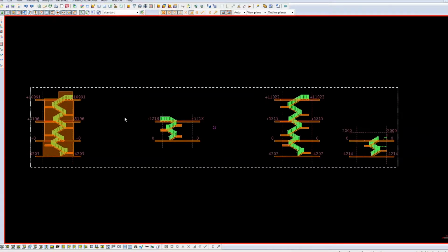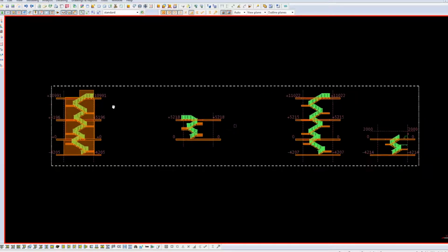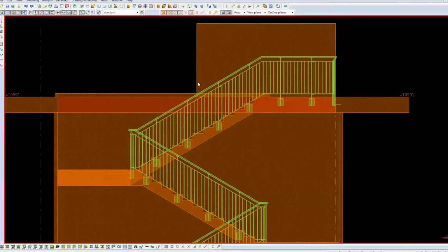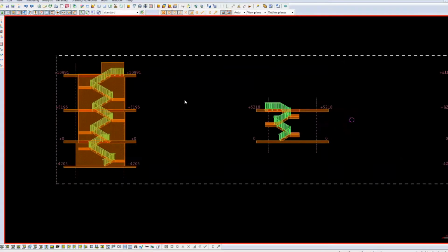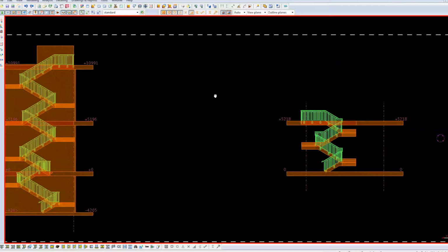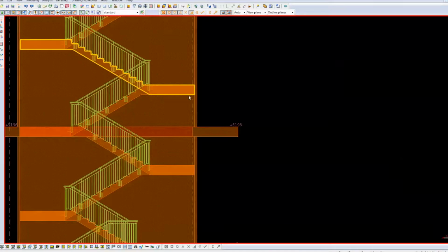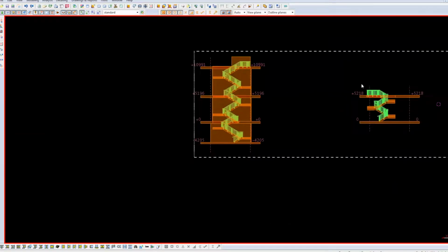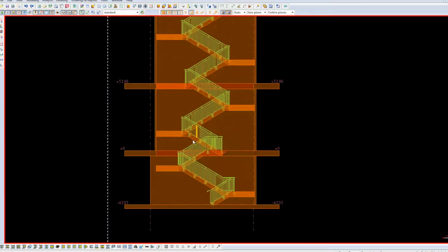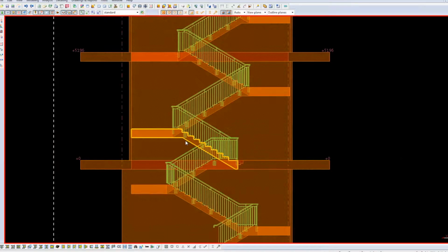This model was sent to me pretty much as you see it by a client who asked if I could just issue the balustrade for fabrication. One of the first things that I did was to compare what had been modelled against the sketched out site survey info. Now, the first thing I noticed was that all the angles of the stairs are all different, and they varied up to about 3/4 of a degree, a little bit more maybe, from memory.